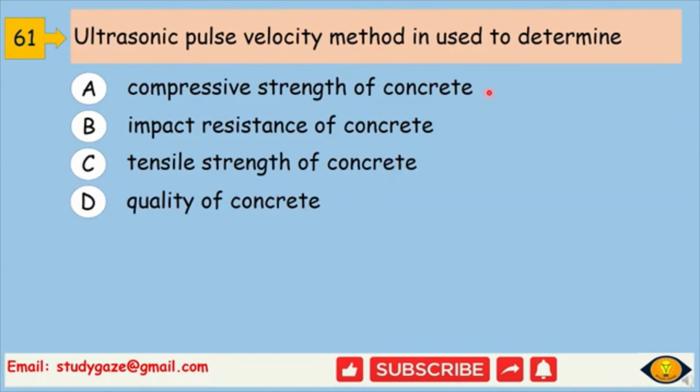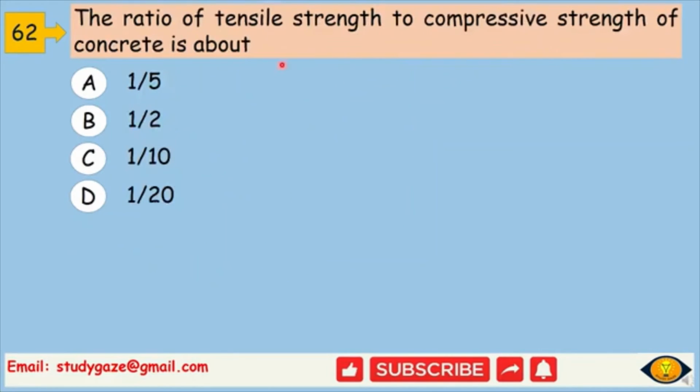61. Ultrasonic pulse velocity method is used to determine compressive strength of concrete, impact resistance of concrete, tensile strength of concrete, quality of concrete. Answer will be D. Quality of concrete. 62. The ratio of tensile strength to compressive strength of concrete is about 1 by 5, half, 1/10, 1/20th. Answer will be C. 1/10.